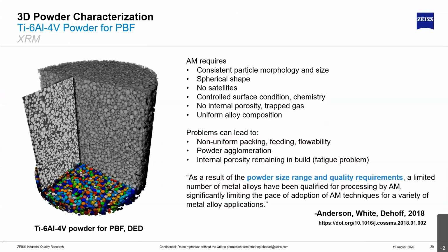So here, at any given point of time, we're able to sample about 100,000 particles. It gives you very, very nice statistics. At the same time, it is the only tool which gives you full 3-dimensional detail on the particles. At the same time, we're also able to look at the porosity present inside the powder particle itself, because this gas porosity from inside the powder particle often stays inside the part as well.